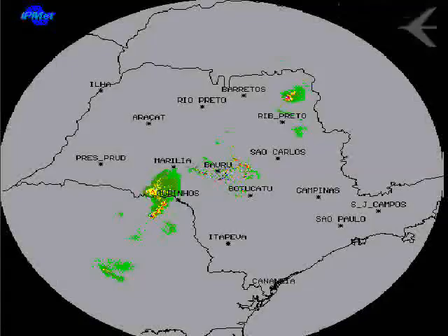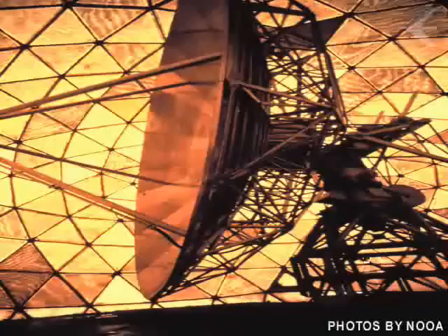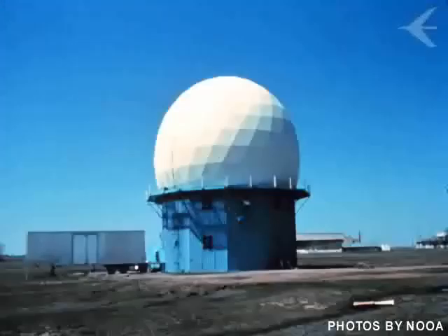Pilots should learn about what is available from center, approach, and tower in terms of weather depiction capabilities. It is important for pilots to understand that calibration rates for image colors found on crew lounge weather radar depictions may not correlate with the rates that are associated with onboard weather color returns. However, some approach surveillance radar comes very close.